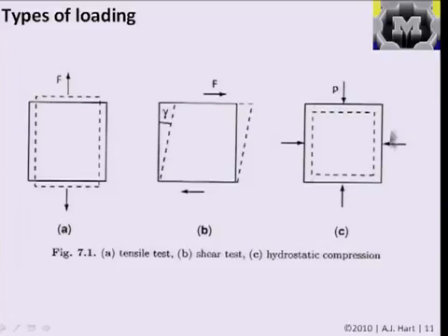And we saw in one of our first lectures that because of the surface pressure, the effective surface energy, because of the dangling bonds around the surface of a nanoparticle, there's actually a very high internal pressure in a nanostructure, and this can change the lattice spacing, or the spacing between the atoms. We had a plot from experiments where we saw that for gold nanoparticles, and remember the change was really small, it could still be measured using X-ray techniques that precisely measure the spacing of the structure. We'll also see an example today for carbon nanotubes where this built-in strain, this built-in stress, can also effectively change the mechanical stiffness of the nanotube. These changes are small, but they can be quite profound and interesting when we get to the small size scale. With nanotubes, we know the chirality, we know how that relates to diameter, and because we can index them based on that, we see changes in the Young's modulus as the diameter goes down, based on the chirality and the orientation of the bonds with the axis of the tube.